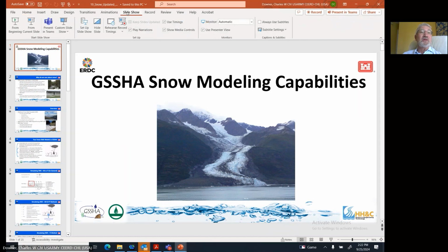Here's a question from Rosie. What sort of data sets do you need to run these different applications? What if you don't have any observed measured numbers? You can get the hydrometeorological inputs that you need from any airport, no matter how tiny it is. There are NCDC data sets, called 3280, or at least it used to be. Anywhere there's an airport, they'll have the data that you need to input it. And that's really all you need, is the temperature data.